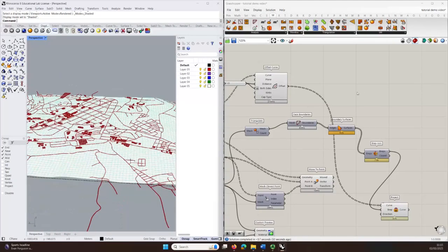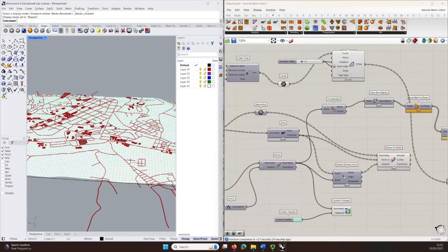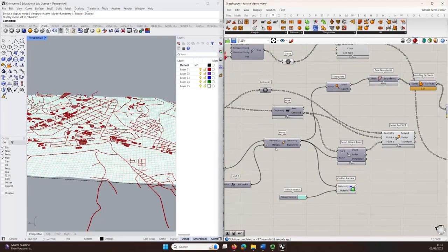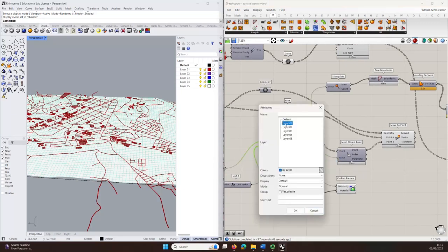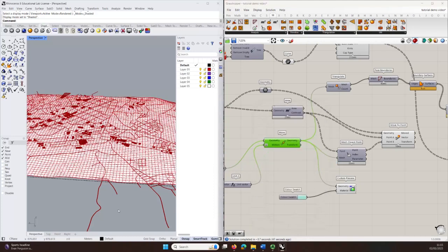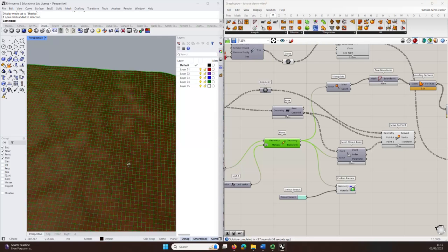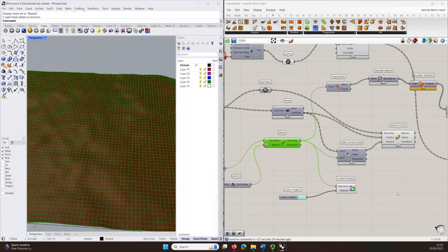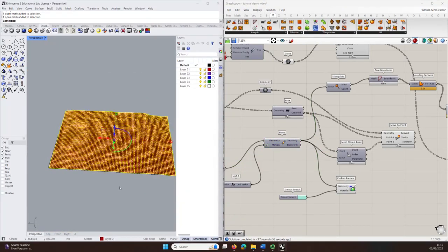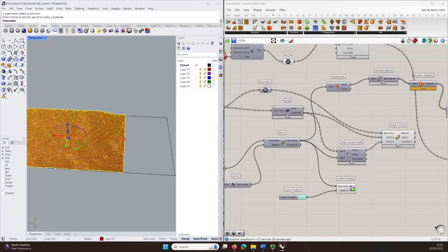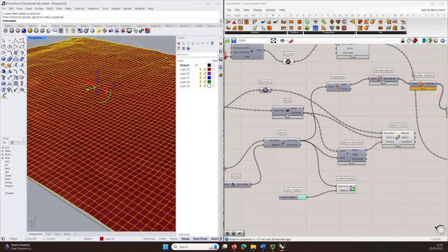And then what you can do, if you don't want to work with this in Grasshopper, is export this through Rhino. So I take my mesh that moved up here and I can bake it. Just bake it, let's say layer 1. And here we go. If I turn everything off in Grasshopper, I'm in Rhino, and I have this nice little mesh I can work with. I can move it around, I can play with it. I can start cutting things in it.